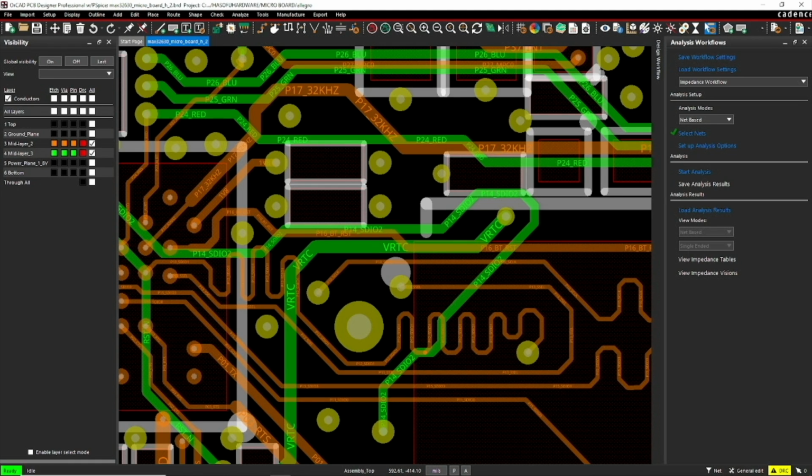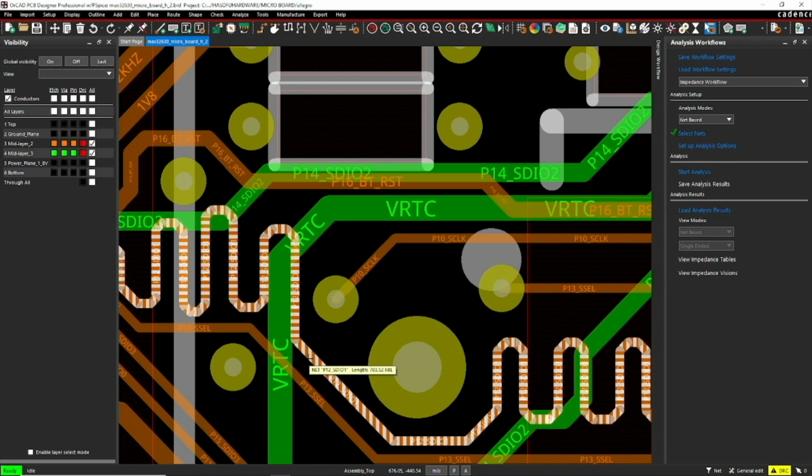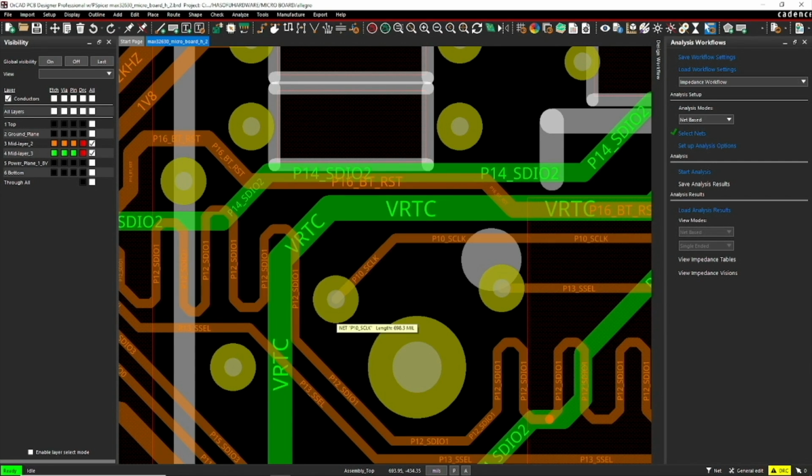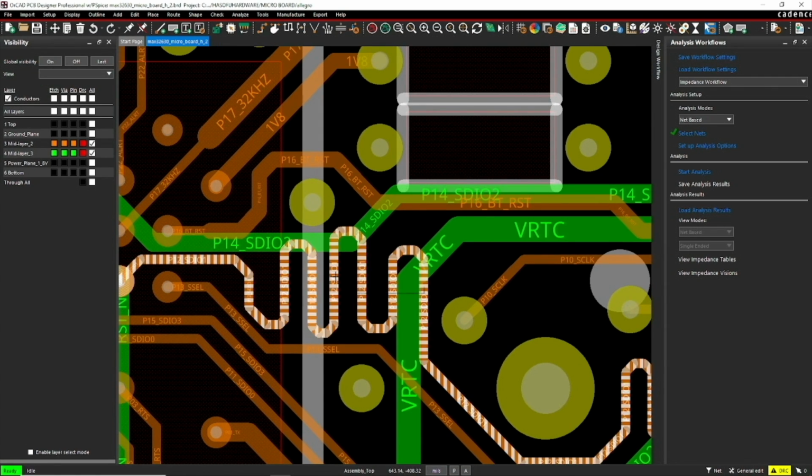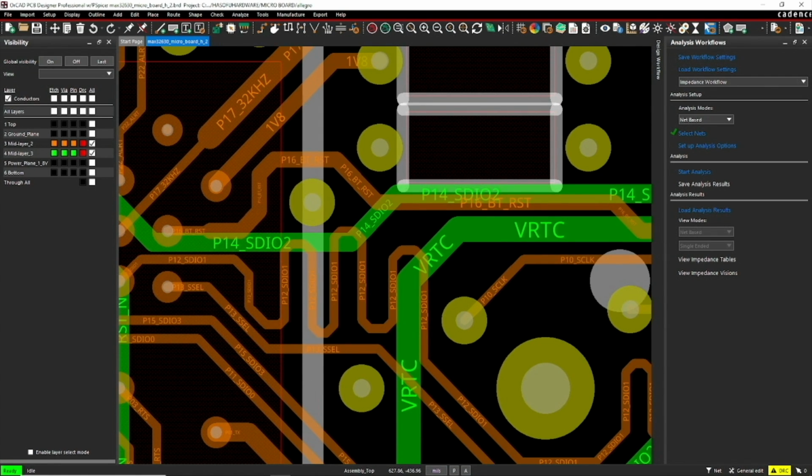Given the fact that materials like signal traces, copper, and dielectric materials slow down the transmission and propagation of signals, we can use them to control when we want the signal information to arrive at the receiver pin. So we can meander the trace about the PCB to slow down and change the arrival time of the signal from transmitter to the receiver.